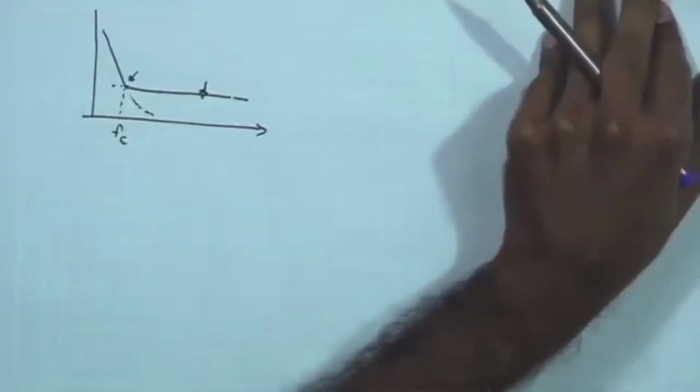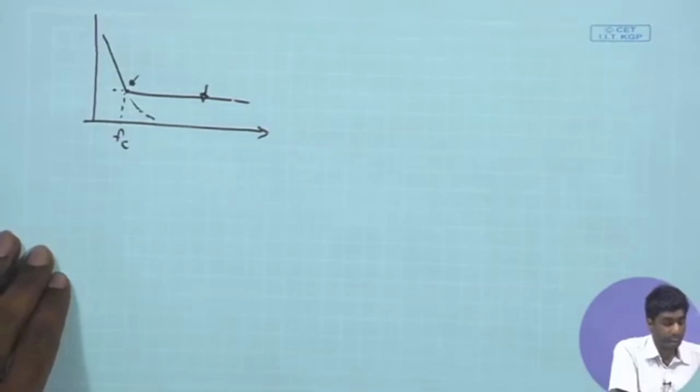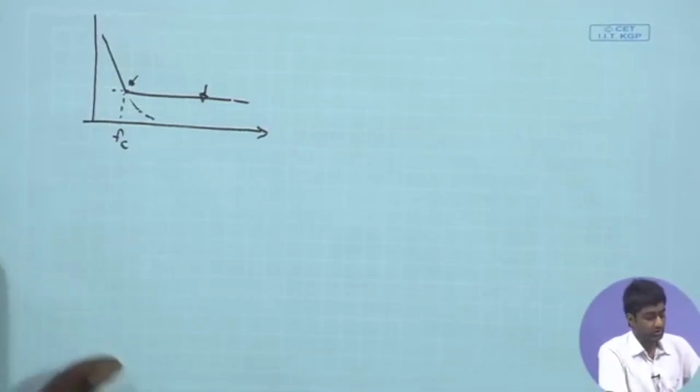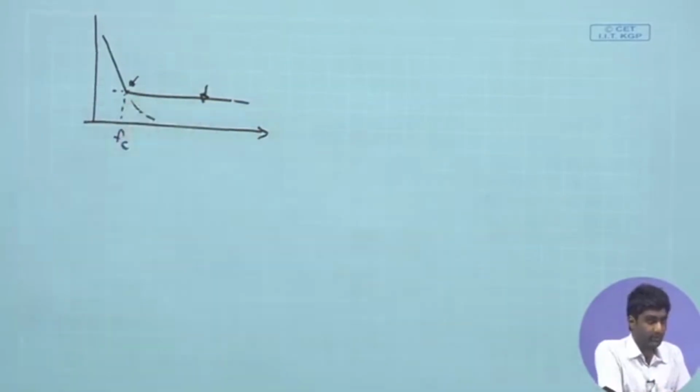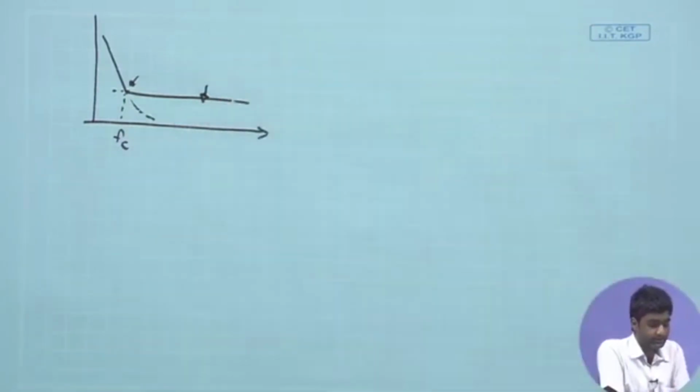Welcome back, and let us start with our resume of the discussion on noise. We will be looking at the differential amplifier circuit with active load that is being used for building our op amp, and then we will be looking at some of the sizing issues related to reduction of this corner frequency 1 upon F, and also look into some other techniques that can be used to mitigate this 1 upon F noise, which also involves trade-offs with some other design metrics. So, let us look at these topics one by one.